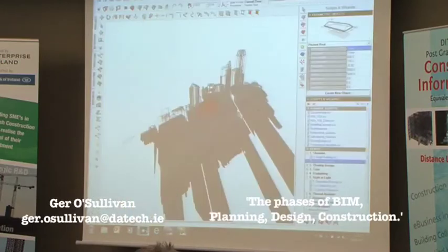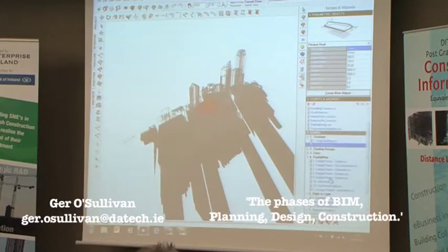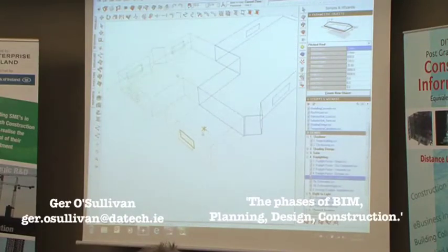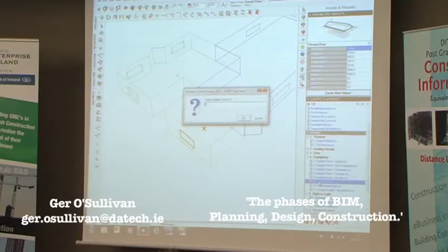Again, various products, as I say, and we can go back out into EcoTips again, and we can look at something like daylight factors. Just something like this, where you saw the glazing that I had put in. Now, let's just say we were wanting an actual target percentage daylight. We were going to say we want it to be 5%, 6% at that particular point in that room. Okay? So we have basically placed a very simple window, it's only an opening, and we can run a script on that. And what the script will do is, it will ask me, well, what percentage do you want of light at that point in the room? And I will say, well, let's put in 6%.